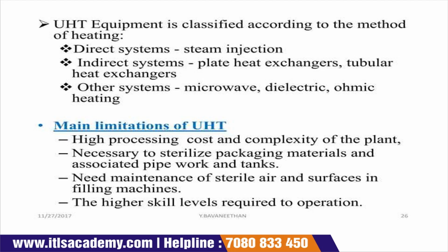UHT equipment is classified into direct systems, indirect systems, or other systems. In the direct system, steam is injected directly into the food product. In the indirect system, we use a plate heat exchanger or tubular heat exchanger. Microwave, dielectric, and ohmic heating are other systems.